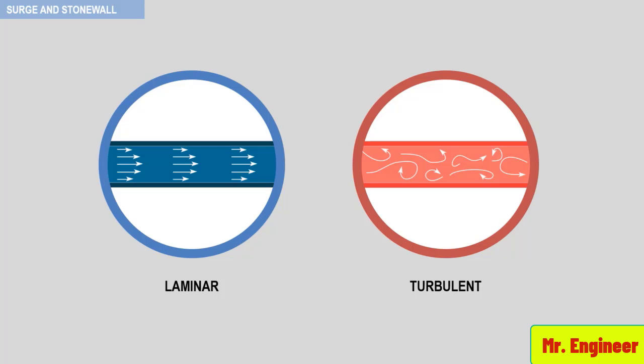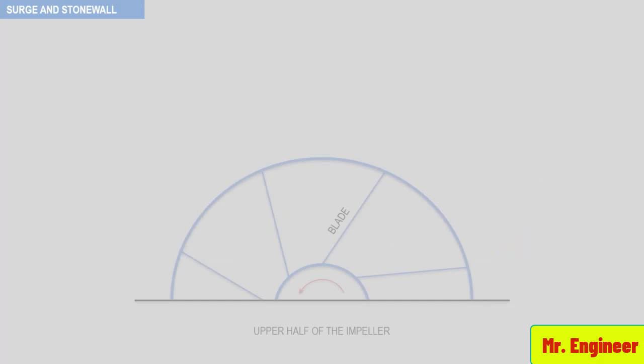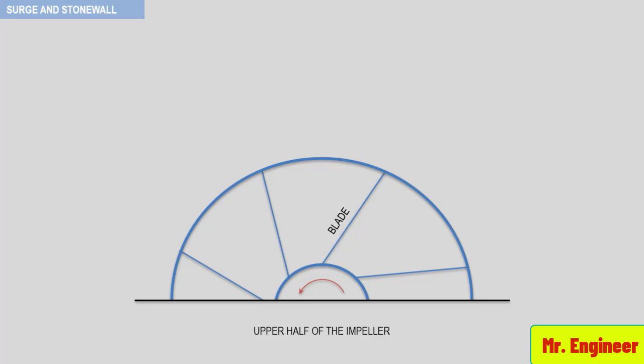Referring to a cross-section of an impeller and a stationary diffuser, we can see and remember from previous discussions that the gas angle of the absolute velocity of the gas exiting an impeller will reduce as the flow decreases. This was explained in details in a previous video, but is depicted here once again for a reminder.